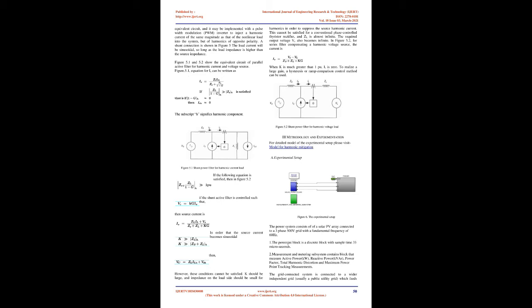Active power filters can be used to filter out harmonics in the power system which are significantly below the switching frequency of the filter. Active power filters are used to filter out both higher and lower order harmonics in the power system. The main difference between active power filters and passive power filters is that APFs mitigate harmonics by injecting active power with the same frequency but with reverse phase to cancel that harmonic,